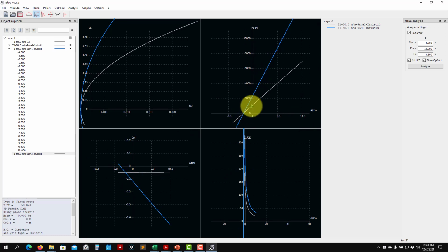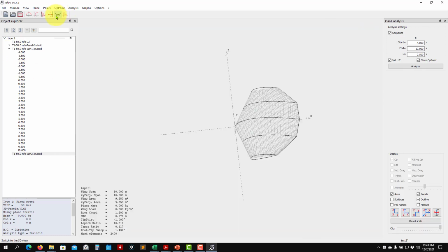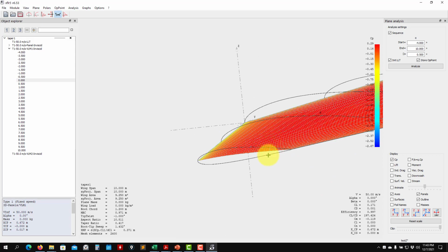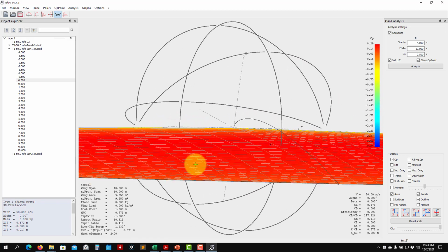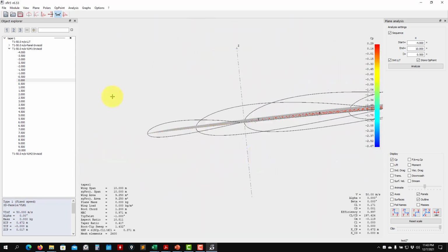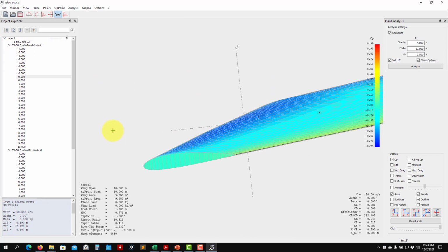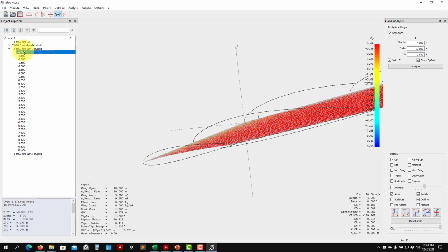And here you go. You have two different methods as you go here in the airplane. And let me show you that the vortex lattice, what it is solving, see that is the camber line. You have the airfoil definition and it will compute the camber line. That is what it is resolving. Instead, your panel method is resolving the whole stuff. Personally speaking, I prefer the vortex lattice. They are very robust, and you can use it for everything, for a complete definition of the airplane, tail, empennage, fuselage, everything. Instead, panel method will have limitations.